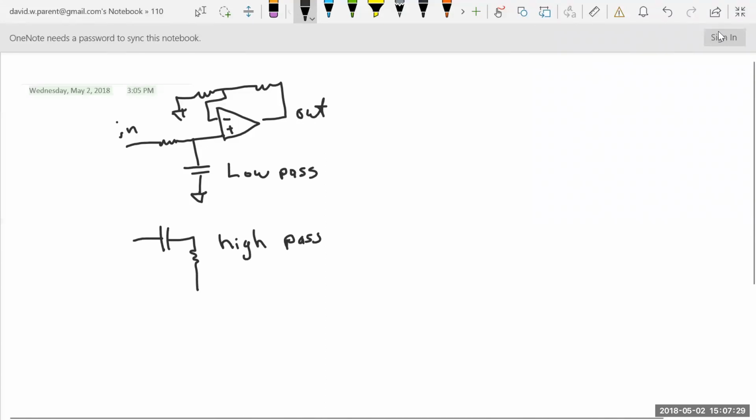And when we first did that on midterm 1, the op amp was modeled like this, right? Right, that was the op amp model. Now, in general, on any interview, that's kind of the first thing you're going to do. This is ideal. It's non-inverting. That's a non-inverting op amp with a gain of 1 plus R2 over R1, right? That's the first thing you learned in EE98 or your original circuits class.